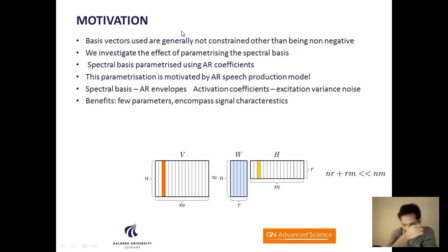In this work we show that if we model the noisy signal in the time domain as a sum of autoregressive processes, the maximization of the likelihood corresponds to performing NMF using the Itakura-Saito divergence as the optimization criterion.